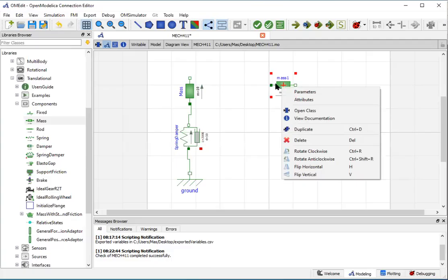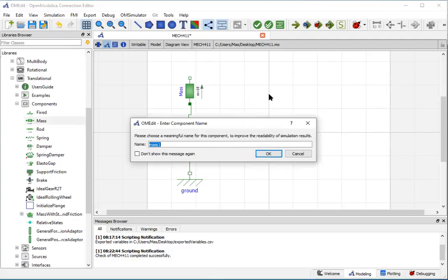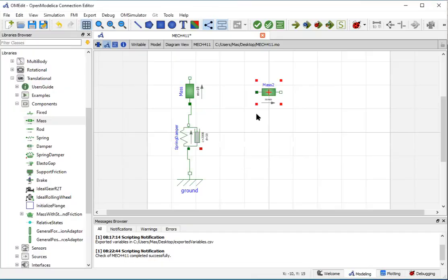Let's just do it again, just want to do it while I'm importing it. Call this mass 2, because I already have a mass there. So I'm going to rotate it, keep it upward, everything. Also, you know what? Let's do it this way. You can do it in either direction. The way you arrange these does not change the results you get. Since it's a forced vibration, a spring mass damper, I'm still going to have those 3 elements I used before, right? So I have a spring mass damper.